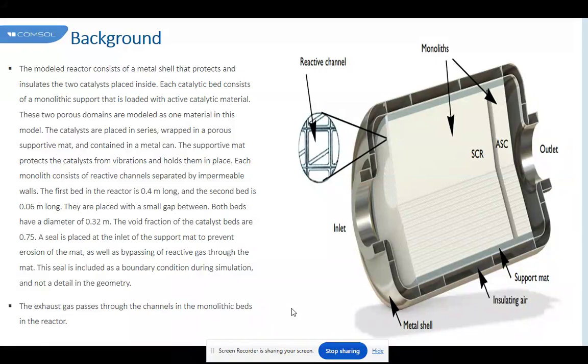In the TWC, nearly 60 to 85% of the cumulative emissions occur before the converter light-off, which takes about 10 to 18 seconds, depending on the catalyst loading, location, and other factors. This length of time also depends on the thermal capacitance of the converter, and the exhaust gas temperature and the velocity at the inlet of the converter. Metallic substrates have a higher heat capacity compared to ceramic for the same volume, but the total thermal capacitance of the metallic monolith may be comparable or lower compared to the ceramic monoliths due to the thin walls.